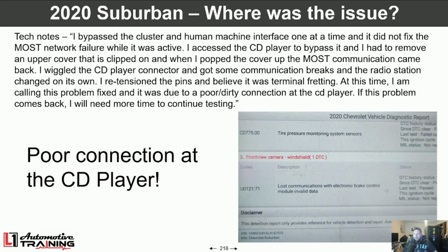The rest of them you can't really... what's funny is on a LIN bus or on a GM low-speed LAN as well, but you don't quite get the information about the MOST bus system until you look at the data in the MOST node master, which is the radio. So that process of just understanding how the system's designed, what does the architecture look like based on RPOs, what do we have and not have, okay, we can talk to this and this, looks like our communication break has got to be at this one spot.